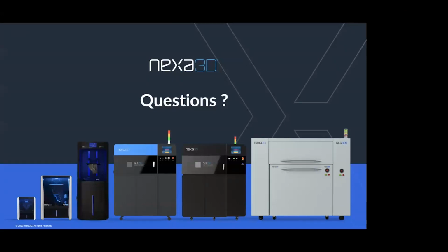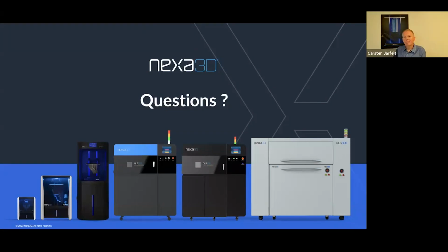I don't know. And I have quite a bit of experience with urethane casting, so I'll add to it or provide a succinct distinction, and that really is, from a material standpoint, you're molding in production grade thermoplastics, everything from your very common ABSs and things like that, to some really high performance plastics like carbon filled PEEK. And this material is compatible with that.